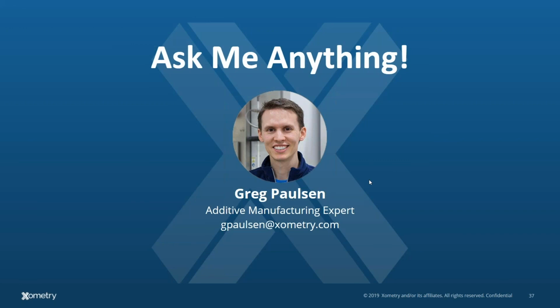Silicone printing. So Carbon DLS has their SIL material. I haven't played with it other than sample materials, but it is very promising for silicone printing. Silicone has been one of those newer achievements that has been more exciting over the last few years. In the industry, putting on my Xometry hat, what I look for is something that is highly repeatable and has multiple providers, so we could use our Xometry network and we're not putting all our eggs in one basket. If one provider goes down, say there's a storm in the area, we don't shut down an entire product line.